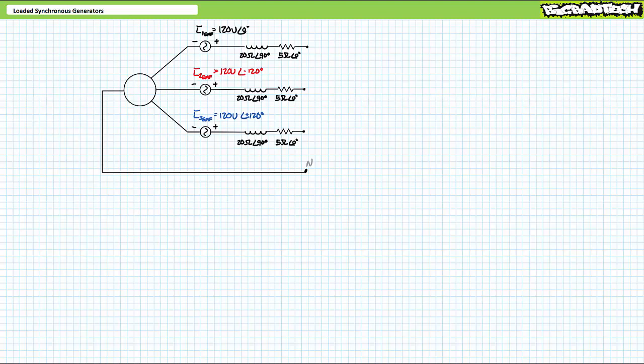In the unloaded condition, this is the one scenario in which a generator output at the terminals of the stator is equal to the generator electromotive force, principally because with no current flowing through the non-ideal internal stator components, there is no voltage across these elements, thus no losses. In this example, in the unloaded condition, we would observe an output line to neutral voltage of 120 volts, i.e. the generator electromotive force without any losses.